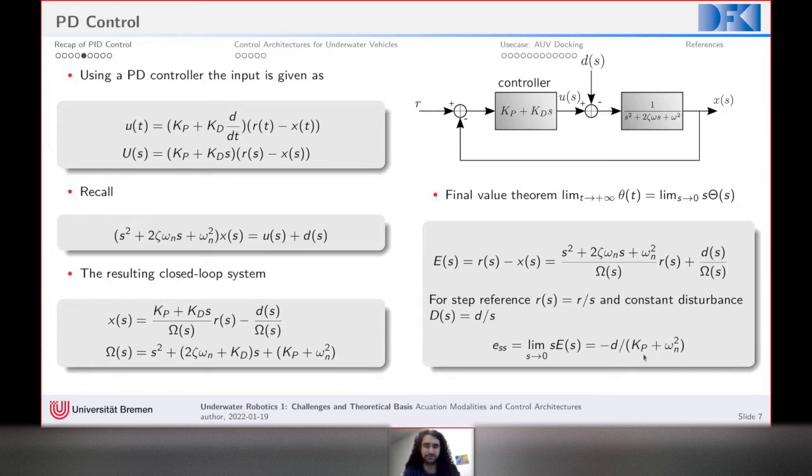This means if I choose Kp to be very large, I can get rid of this disturbance in there, right? As this tends to be a very large number, the whole thing tends to be a low number, which is the error that I'm trying to get rid of, because this disturbance is also causing me more error that I don't want.